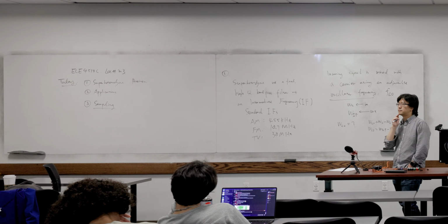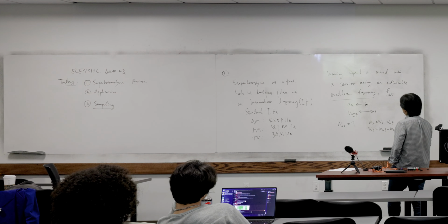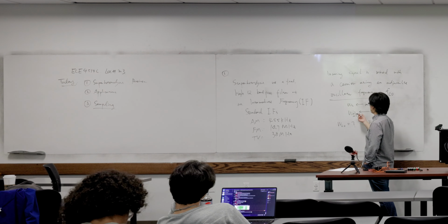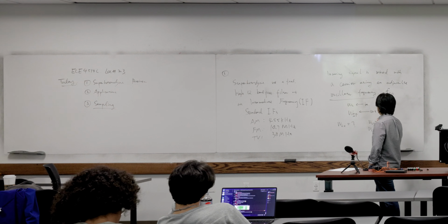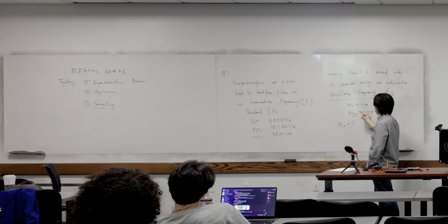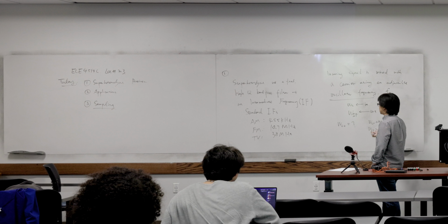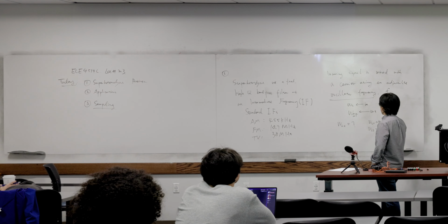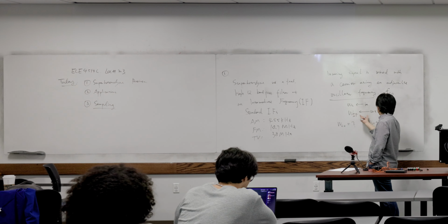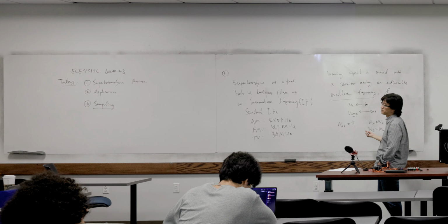Any other options? Yeah, so basically, if we pick this option, the output frequencies that we have are omega c plus this, and omega c minus this, right? So we'll have omega c minus this, then we'll have omega f, right? Yep, seems working, right? But the other part is 2 omega c minus omega f. And if we pick this one, when this minus that, we have 2 omega c minus IF. When we do this plus that, we have omega IF. Yeah, it seems working, right?